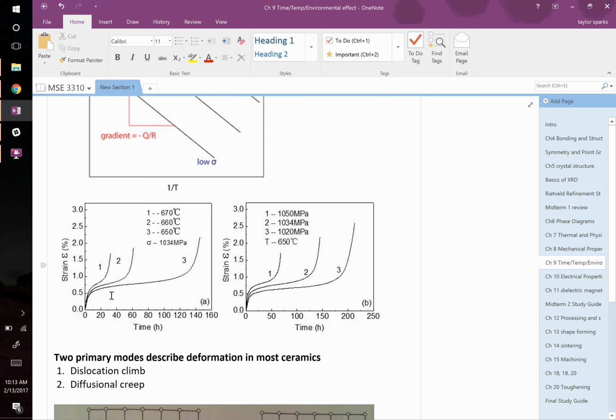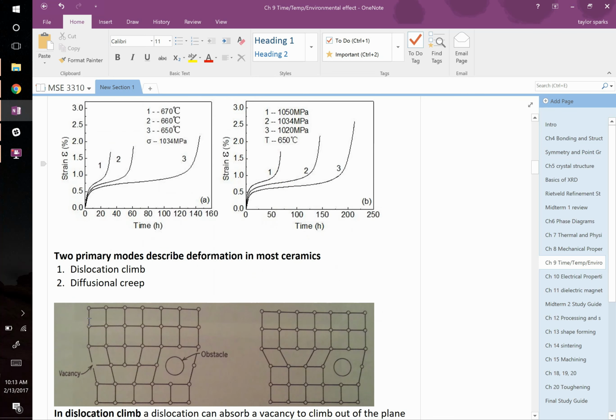I think we mentioned this in 2010 that you'd like to measure like how long is you want to know the creep of material for a roof, but you can't just build a roof and let it sit for 20 years and make that measurement. You can, it's just not very efficient. So what do we do instead? You take advantage of this. You either increase the load beyond what it's actually going to be under, or you increase the temperature, or you can do both, right? And if you do both, you can determine what these creep constants are, A, N, and Q sub C. Once you know those, you can determine it at any arbitrary stress or temperature, assuming you're still in the secondary creep range, right?